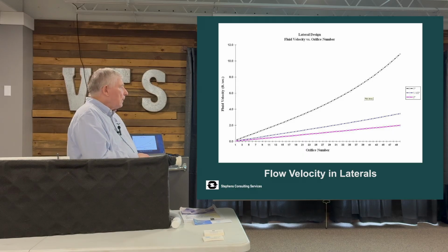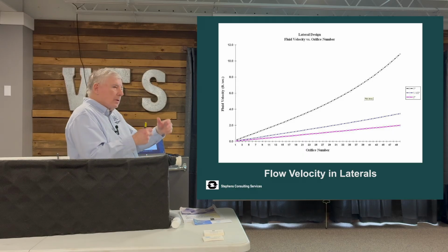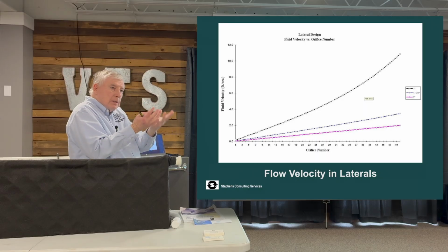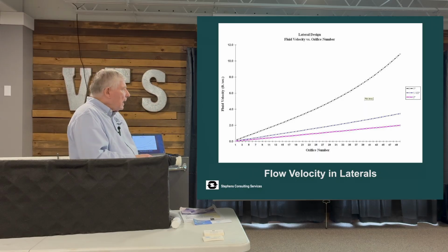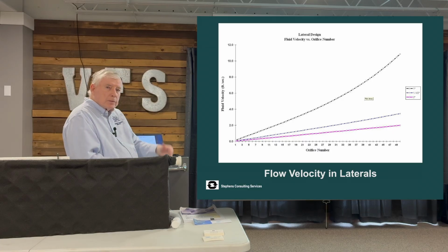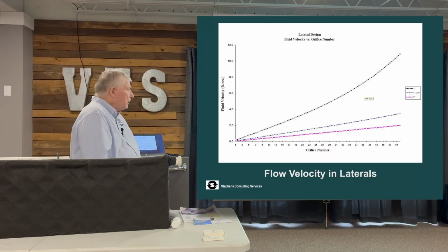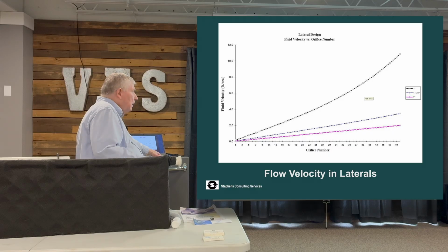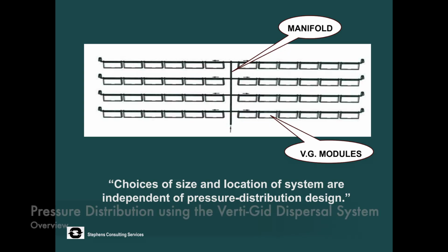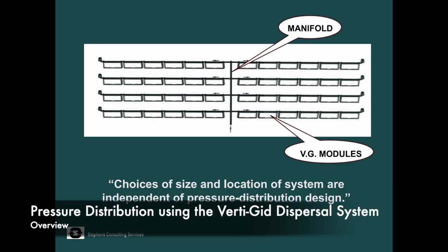But with a smaller diameter, you're kind of balancing this with good velocity. Here by about 12 orifices, you're up to 2 feet per second in a small diameter pipe. So you will get some scouring velocity. So it's an engineering balance to try and figure that out.